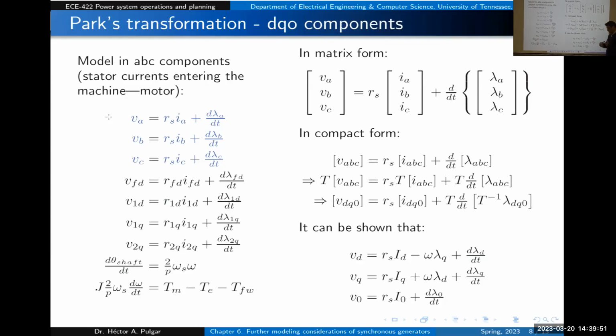But this is going to be the transforming voltage. This is related to those quantities that in a steady state should be 0. This is the flux linkage in the D axis and the flux linkage in the Q axis. These, as you can see, and this is the beautiful part, do not have any term that depends on time directly.